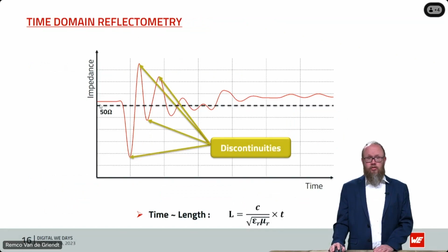Here you see, for instance, how it looks. You have here normally a 50 ohm trace impedance, which is really normal for an SMA connector. You see really big discontinuities here, and this one is really a change in the geometry of the connector, for instance, and then you see it's going to be stabilized. This could be where you're going from the coax cable to the connector itself, also here above, and then you see it's going to be leveled. Maybe there's some soldering. That's, for instance, again, because I don't really know the measurements about this, because the real measurements I did later on. And you read this over the time, and you really can see here how it's going to be.